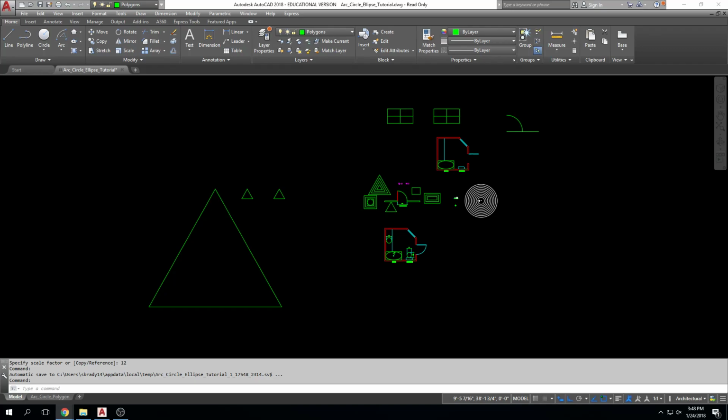So when a set of drawings is opened, the heaviest line is going to be the walls. The heaviest thing that you see is the walls, and you know those are the walls. The second heaviest thing are doors and windows. So you look at it and you say, oh, these really dark things on the plans, those are walls. And those things represented by a symbol that means a door are also slightly lighter in pen weight than walls. So we look at it graphically and can say, the heaviest outline, that's the wall. And the next, that's less heavy, is going to be doors and windows. And then we have furniture, and you can graphically, visually determine what things are in a set of drawings by the thickness of their pen weight, okay?